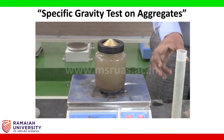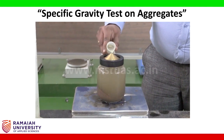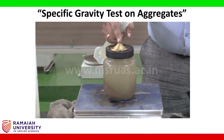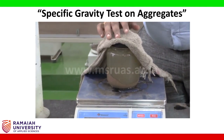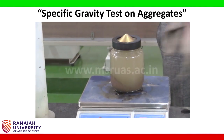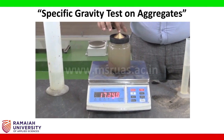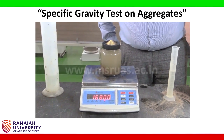Then I'm going to add the conical portion with the water. I'm going to make sure that this conical flask is completely filled with water. I'll remove this excess water which is outside. Okay. After filling the tip completely with water, I'm going to note down W3.